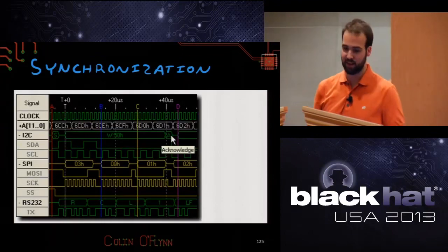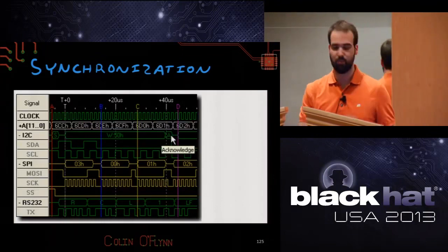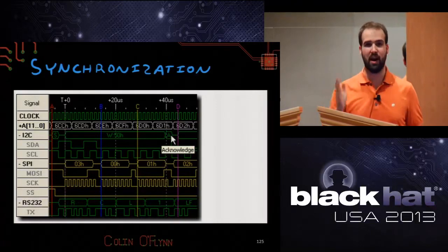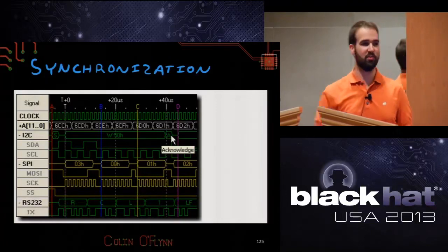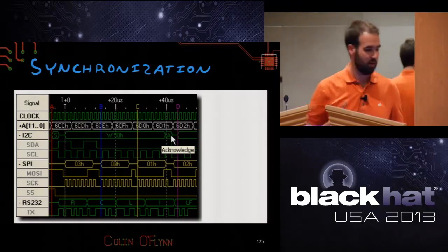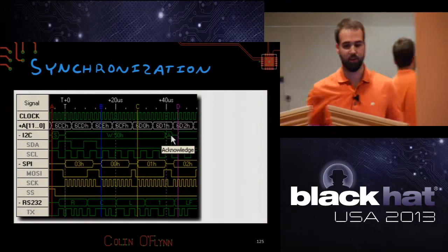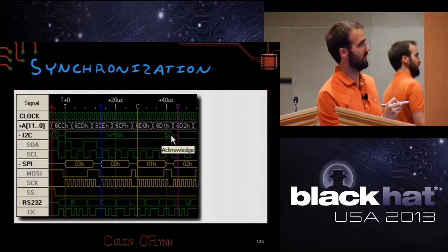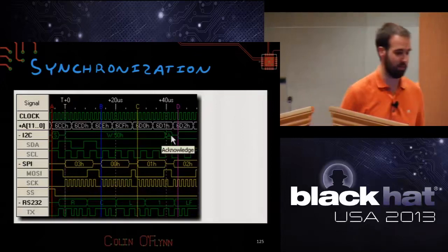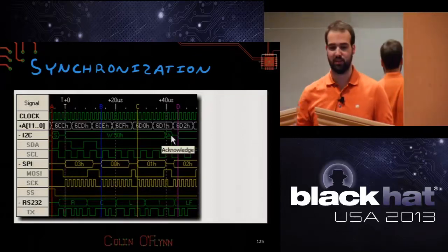The final thing is that right now I'm using the device itself. When I say run this encryption, it says, okay, I'm going to run the encryption. It sets an IO pin high, and this is how I know I should measure the power. What you need to do instead is monitor the IO lines of the device, for example, and say, well, I know when I send it some byte, some binary pattern, then it's going to run the encryption, or maybe it runs it after so many clock cycles.